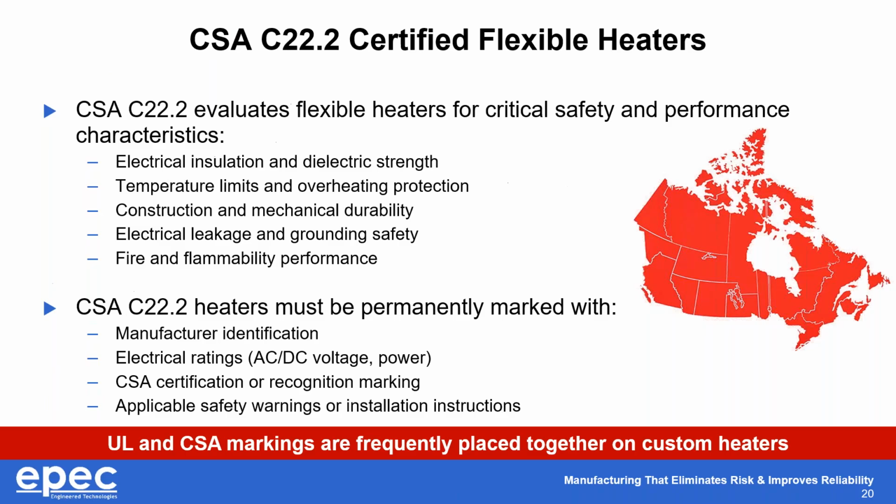Focusing on Canadian product safety markets, the list here of product safety tests is very similar to what I covered for UL. The electrical insulation and dielectric strength, the temperature limits and overheating protection, mechanical durability, leakage current, and flame ratings are all the exact same tests you're doing with UL.